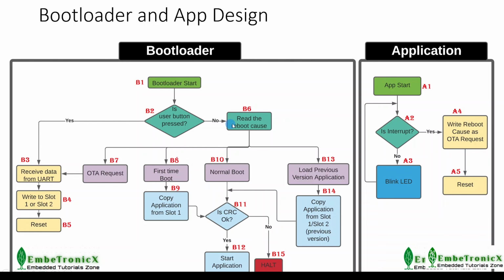If it is a normal boot and not the first time, it will check the actual application CRC, and if that is fine, then run the application. Otherwise, it will not run the application. If the reboot cause is an OTA request, that means the application has requested the OTA firmware or application update. In that case, the bootloader will receive the data from the UART and store it in one of the slots.